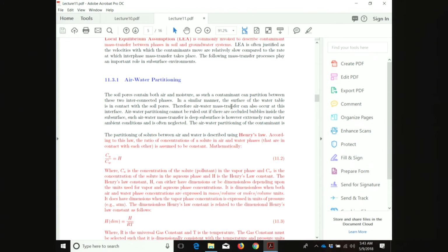So to convert from pressures, we divide it by RT, R being the gas constant. This is just coming from the ideal gas law. We can back out. Okay. So always keep track of what units that Henry's law constant is.